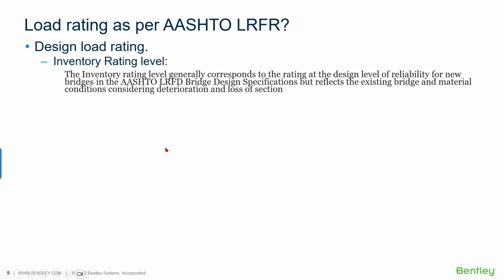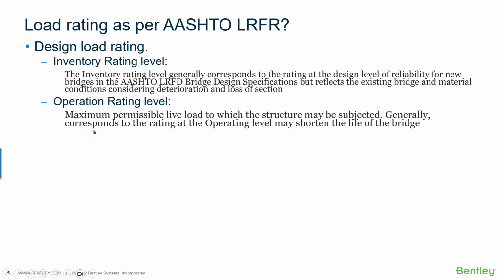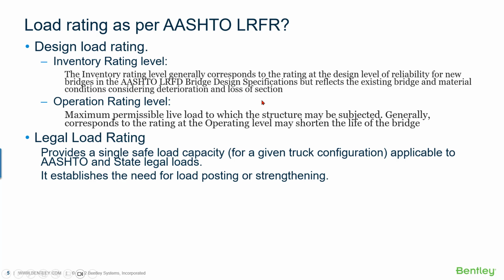So, for design load rating, what do we need? The inventory rating level generally corresponds to the rating of the design level of reliability for a new bridge in the LRFD bridge design specification. But it reflects the existing bridge and material condition, considering deterioration and loss of section. It can also be used for the operating rating level, the maximum permissible live load to which a structure may be subjected. Generally, it corresponds to the rating of the operating level, which may shorten the life of the bridge.